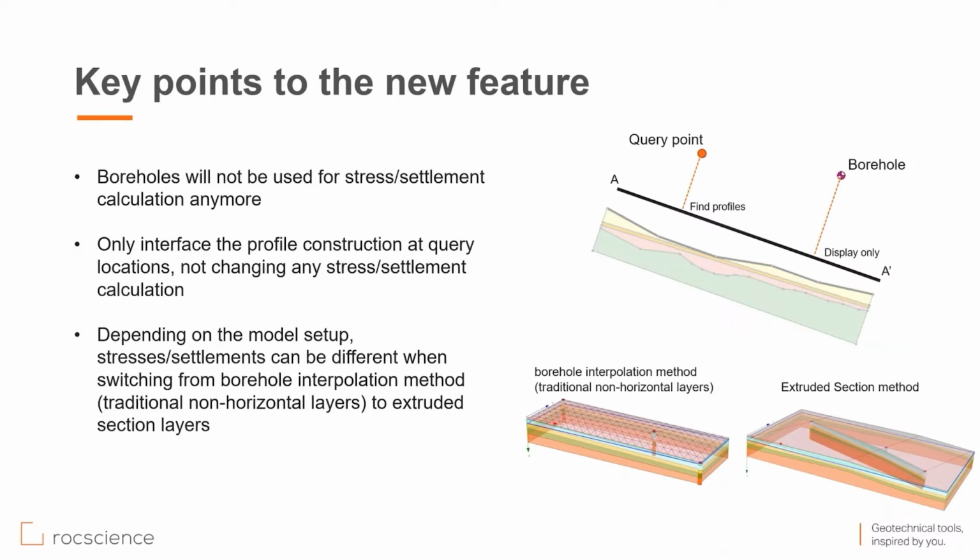There are a couple of key points worth talking about in this new extruded section mode. Because we use a user-defined section to retrieve profiles for the entire engine calculation, boreholes are no longer used other than to guide users in drawing their sections in the section creator. That being said, if you want to, you can even delete boreholes after defining a section without running into any issues. When the program runs any calculations at query point locations, it makes a projection to the section line like this, and then finds the profile at that projected location for this query location.